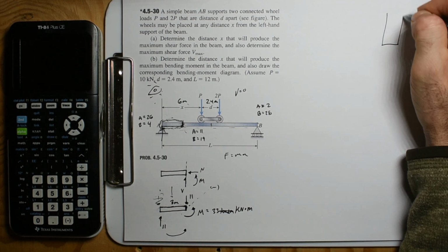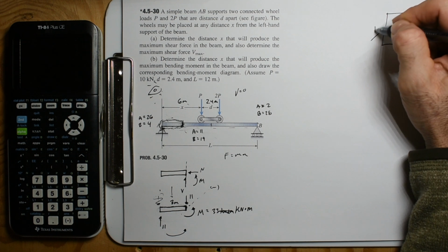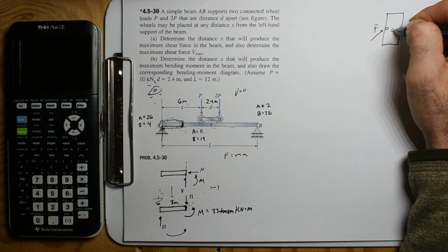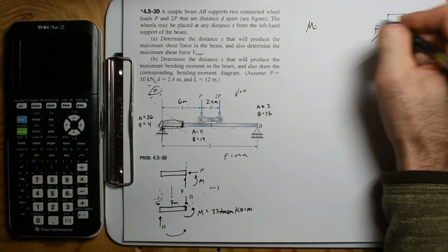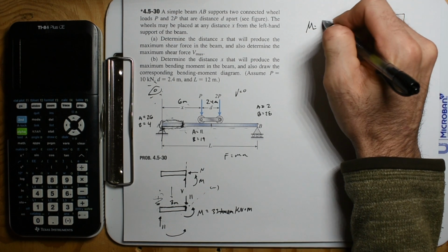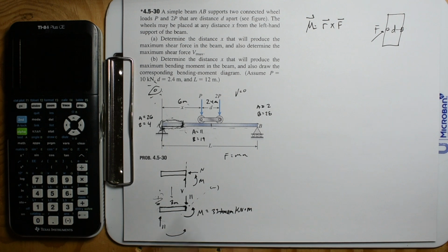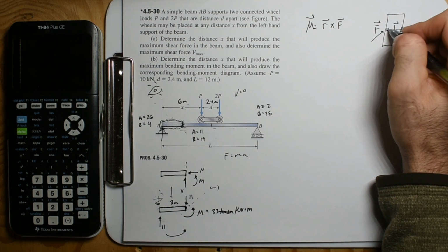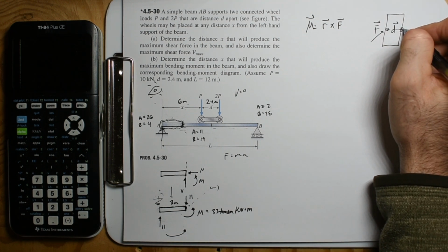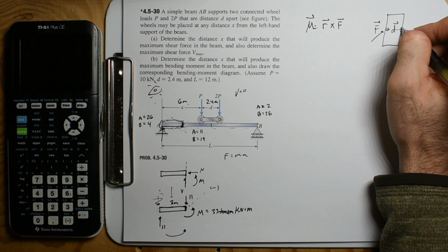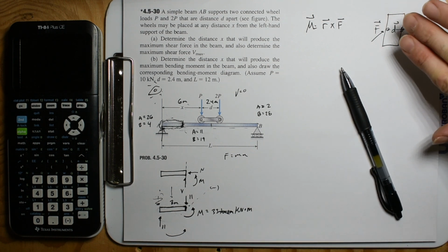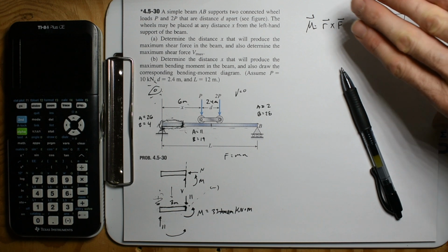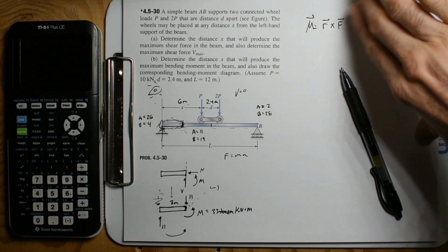Just like opening a door, I'm going to apply a force. And because this distance is this far away from the hinge, just think of moment as leverage. Moment is R cross F, and it is a vector. So here's your force, here's your distance vector. From here, you would start at the hinge using the right-hand rule, putting your fingers in the direction of the distance, and then sweeping in the direction of the force.